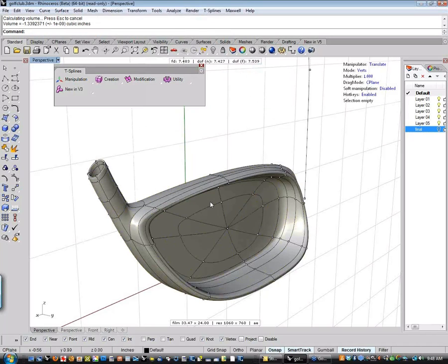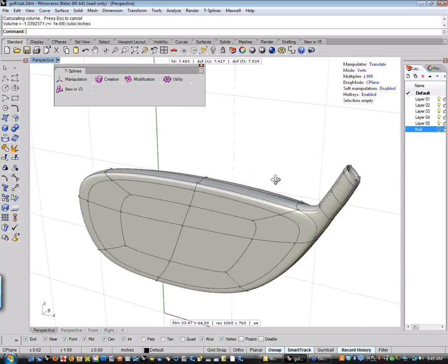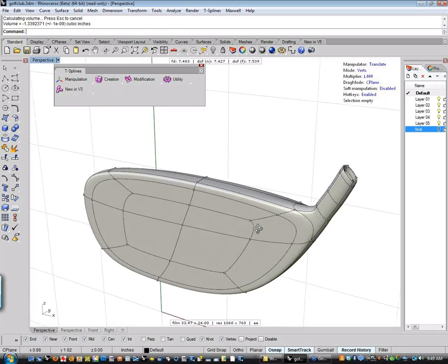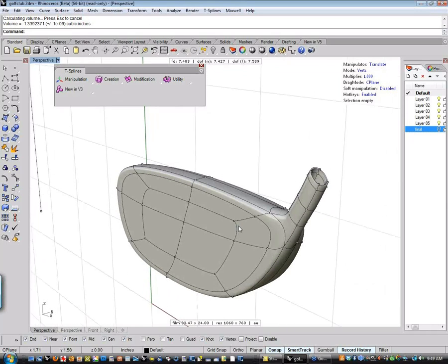3, 3, I'm going in the right direction. I'd need to do that a couple of times in order to get it to where I was. But I can basically absolutely positively nail a specific part weight or shot weight if I need for an object just by using the Rhino mass properties with a T-Splines object.